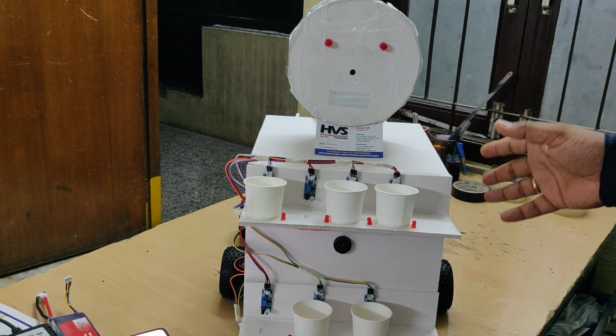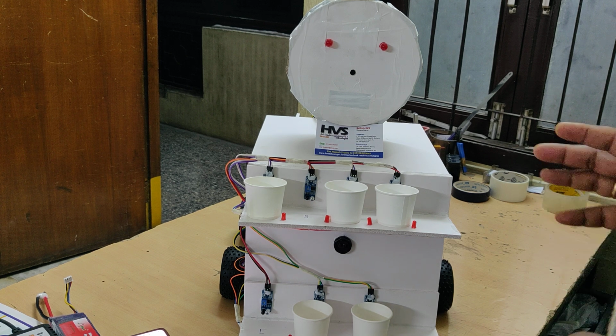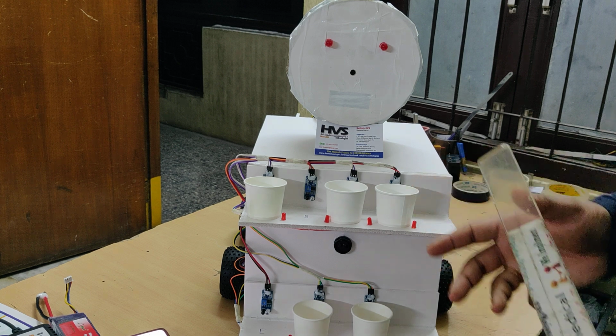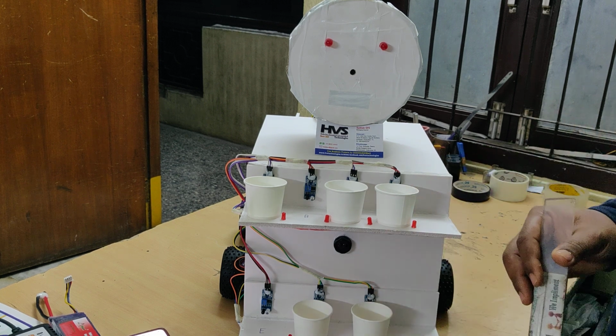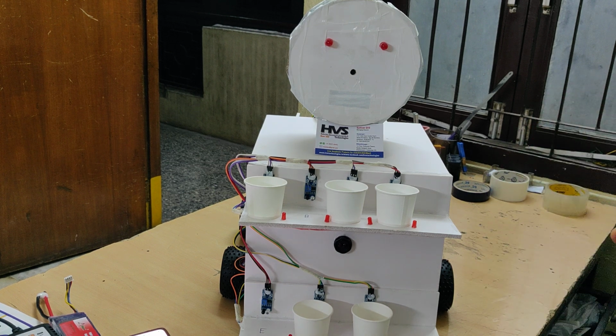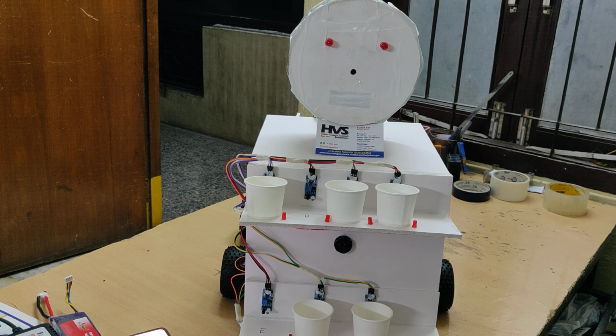So we developed this robot with 4 DC motors which come with encoders. The main purpose of the encoder is, generally a DC motor will rotate in forward and backward directions, but it won't inform us how much distance it has traveled exactly. A stepper motor can provide that, but it can't handle more weight. So that's why we are using a DC motor with an encoder.